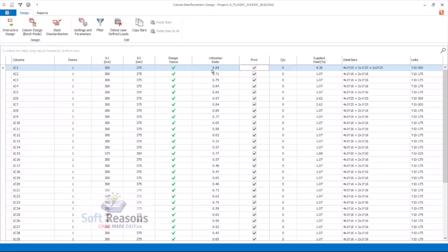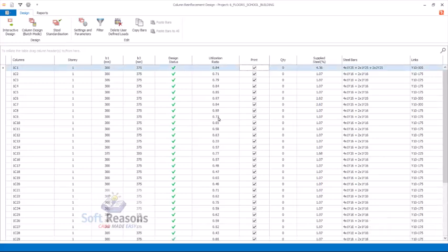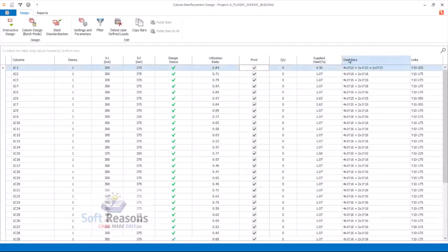So you have to check your U ratio, it is very, very important here. Now we see the maximum U ratio I'm having here is 0.84. If you check the columns, you see the supplied percentage of steel is 4.3, which is the highest percentage of steel supplied. Then you check the steel bars: you have 4Y25, then 2Y25, and then 2 times 2Y25 right here.